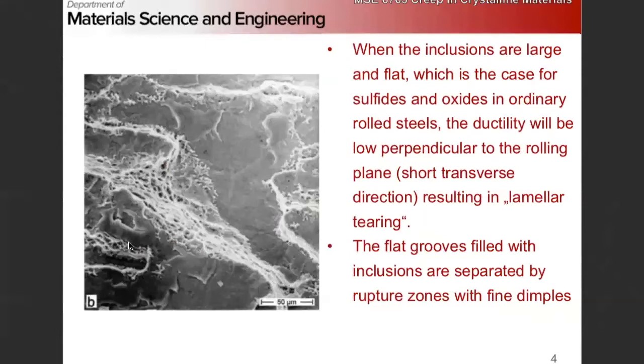They start out spherical, right? And these particles are preferentially on grain boundaries, and then we smash them flat. We do a rolling reduction of 90%. So we make our grains 9 times longer, right? Now we have essentially our particles arranged in parallel layers that are about 1 grain wide, right? And they're all aligned with their flat parts normal to the rolling plane, right?